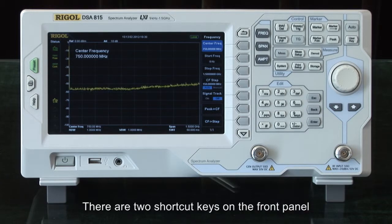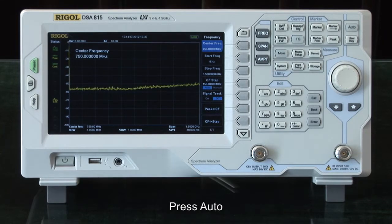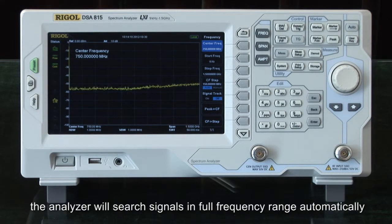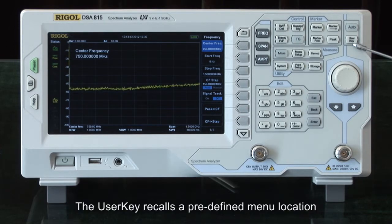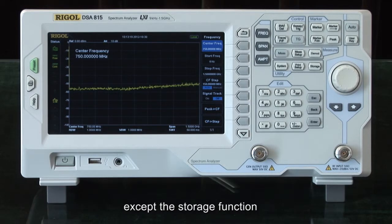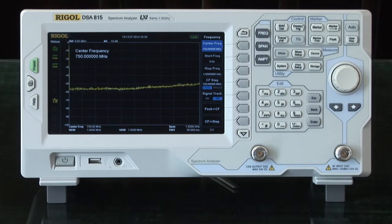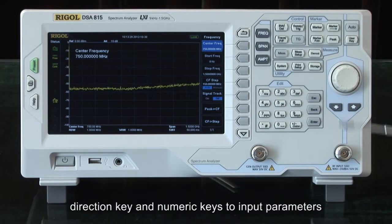There are 2 shortcut keys on the front panel. They are Auto and User key. Pressing Auto, the analyzer will search for signals in a full frequency range automatically. The User key will recall a predefined menu location. This key can be defined as any of the functions on the front panel except the storage function. The above introduction is for the function keys on the front panel. We can also use the knob, direction key, and numeric keys to input parameters.